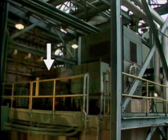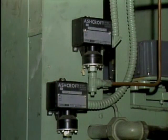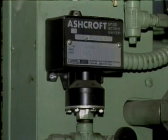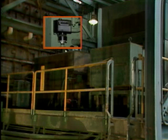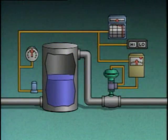An interlock ensures that a predetermined set of conditions exists before the status of equipment is changed to prevent equipment damage or harm to personnel. For example, this fan could be damaged if it's operated without proper lubrication. To prevent damage, an interlock pressure switch opens to shut off the fan's motor when the oil pressure in the motor is too low. The switch remains open to keep operators from turning on the fan by mistake until the oil pressure is high enough for normal operation.